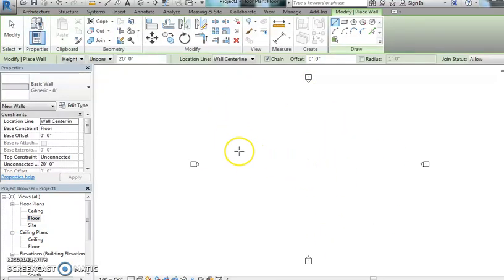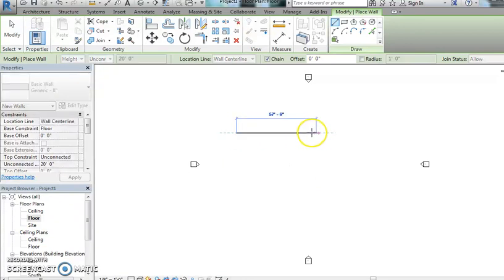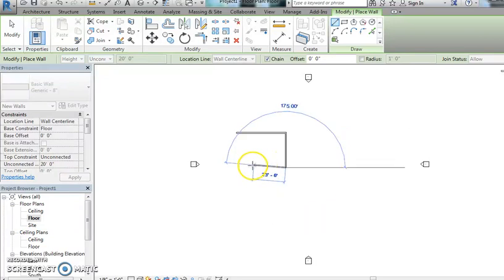And I've clicked wall. You should have this little cursor that shows up. So I'm just going to draw, and that's feet there. It looks really small. We'll zoom in just like in Inventor. I'm going to say it was 35 foot 6 inches. And this side, the room's a rectangle, so that's going to be shorter. Let's say it's 26 foot 6 inches. Okay. Same thing, 35.6, 26.6.